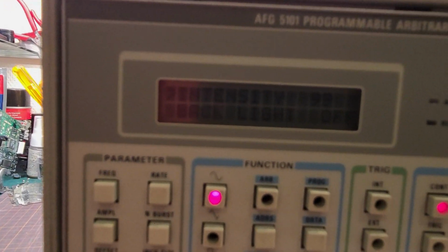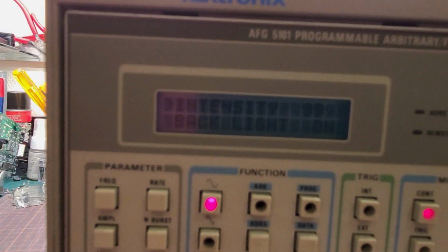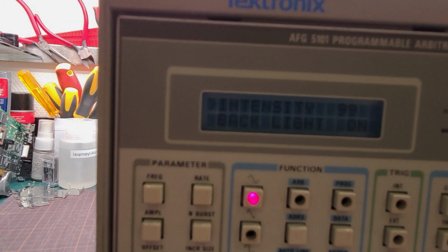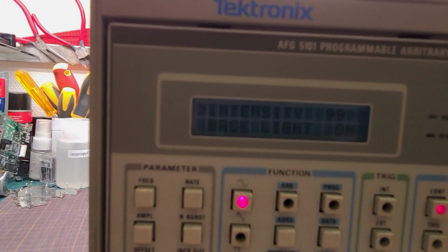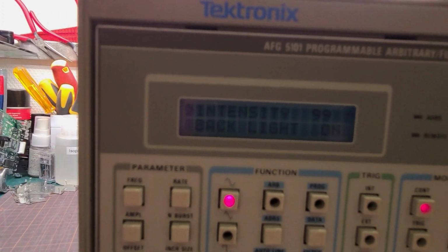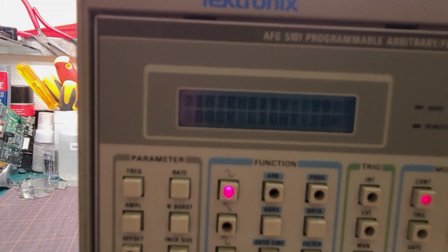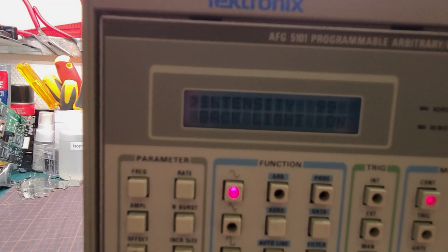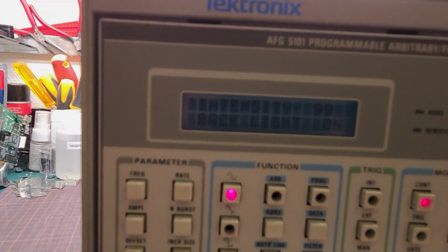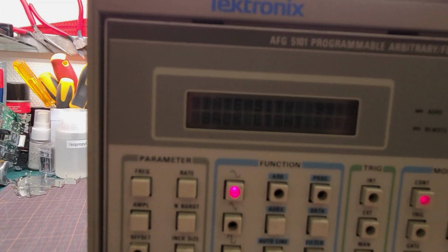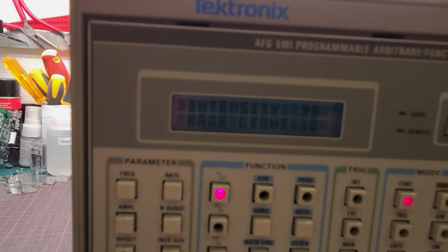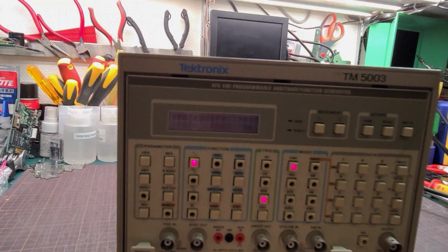And actually, I can hear a really faint whine. I bet you any amount of money that's an electroluminescent panel, because back when this was made, blue LEDs probably didn't even exist. So that is just faded with age. That's just an old faded electroluminescent panel in there. So we have to fix that, and that RAM problem. But that may be the battery, so that might be two birds with one stone with any luck. But yeah, it seems to turn on anyway.